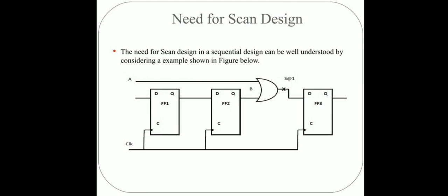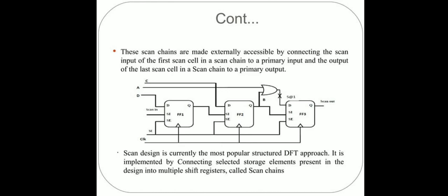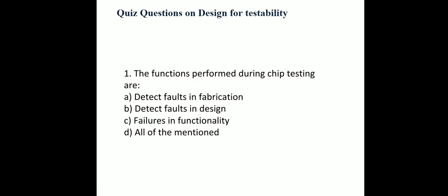We need scan designs because, for example, if we transmit any information, it should be automatically tested so that there will not be any complexity or error inside the fault models. This tries to be externally accessible by connecting the scan inputs to a primary input and the output. This design is the most popular structured approach. It is implemented by connecting the selected storage elements present in the design.